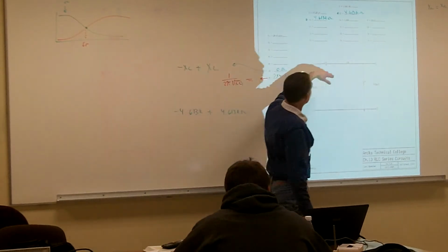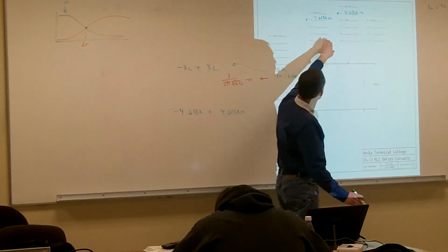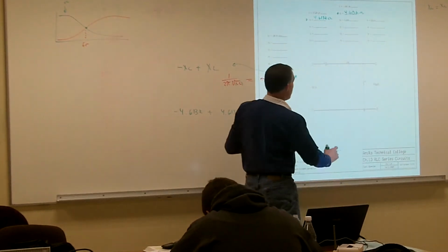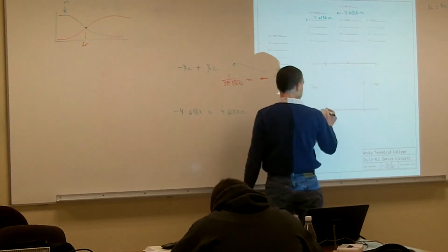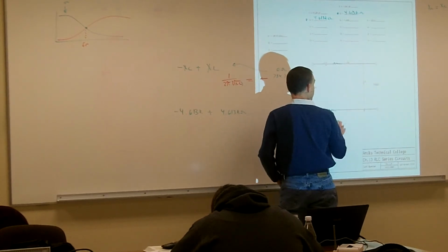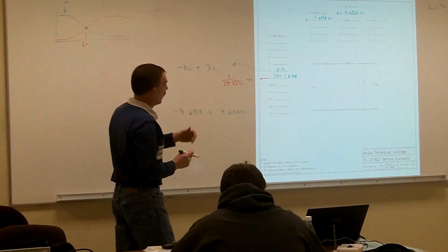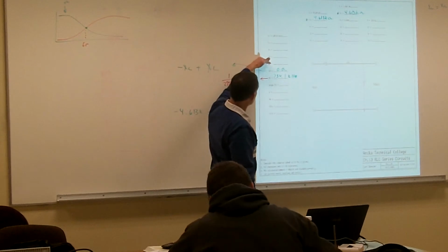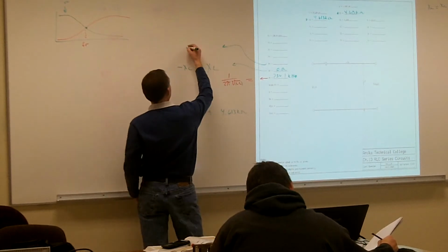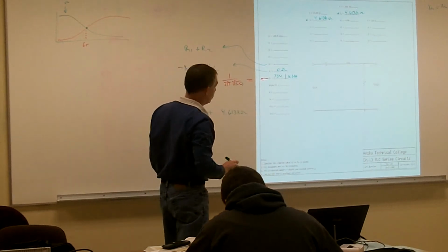Now we can go to our resistance. We have a resistor in here of 220 ohms, and we also have some resistance in the windings of our inductor that we have to include. It doesn't matter where any of this resistance is in a series circuit. I can just go ahead and add them all up. So whether it's inside the inductor or somewhere else in the circuit, I just calculate out my total resistance, like if I was doing a series circuit, R1 plus R2 and so on, and that'll give me my total resistance.